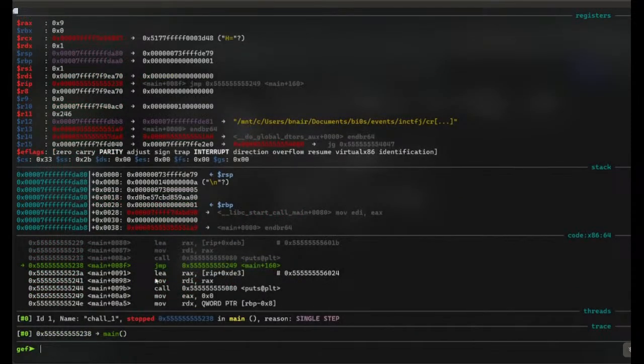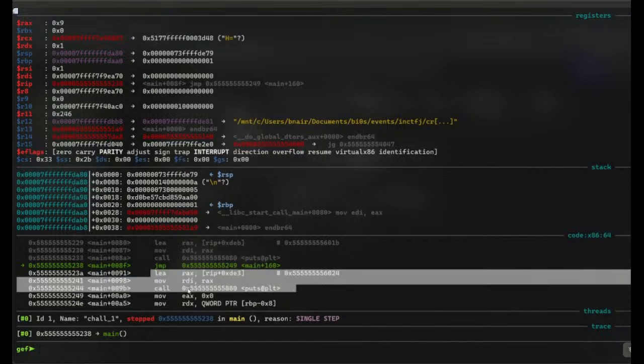Okay. Now what happens after that is JMP. What is JMP? JMP is like jump to this particular location. The other cases also had jumps, but those are called conditional jumps because you have to satisfy certain conditions for it to jump. Now this jump is called an unconditional jump. So when we have this instruction, it means that it will anyway jump to that particular location. So this instruction will not execute these three instructions and will go here.